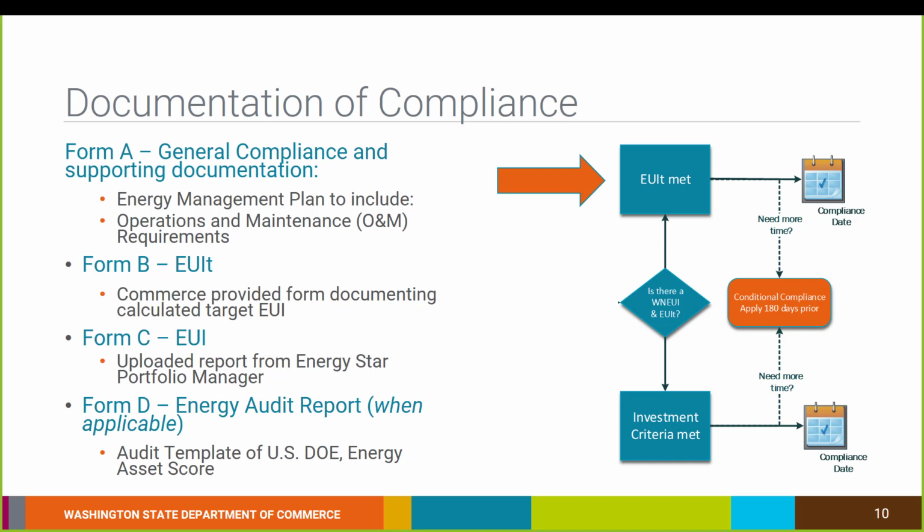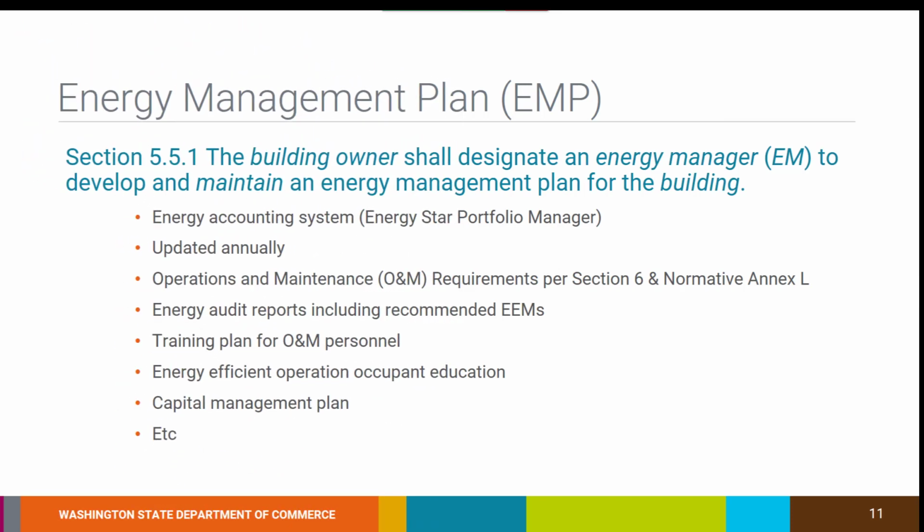As an addition, as part of the energy management plan, any buildings performing an energy audit shall document the energy audit using the U.S. Department of Energy's audit template of the Energy Asset Score tool. A link to this report will be available on the Clean Buildings portal. As noted, creation of an energy management plan is a mandatory compliance requirement of the Clean Buildings Performance Standard and shall be submitted to Commerce through Form A.